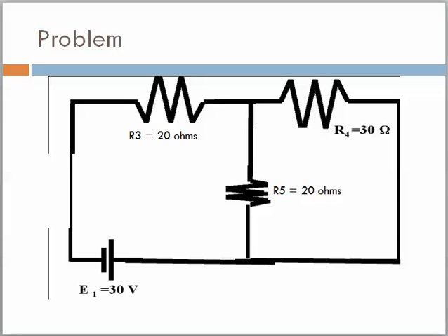If we look at this, both resistor 5 and resistor 4 are in parallel, meaning when the current comes through here, it's got a choice right now. It's got two different paths it can take. This first resistor, even though I've got it labeled here as resistor 1, is in series. It's like our household. It's in a series circuit. If this one were to blow, no electricity could keep going, no current could keep going. The electrons would stop, and the other two would no longer be operational.